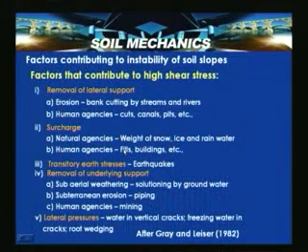Similarly, human agencies like construction of a fill on an existing slope or construction of a building on a natural slope can cause an external loading to a slope. And transitory earth pressures, that is earthquakes, that we have discussed, can contribute to the higher stresses and cause failures to the slopes. And removal of the underlying support: subaerial weathering, that is solutioning by groundwater, because the groundwater dissolves minerals and can cause subaerial weathering. And subterranean erosion, that is called piping, when the water flowing through the slope can cause a piping failure and erode the soil. And human agencies like mining can create removal of the underlying support.